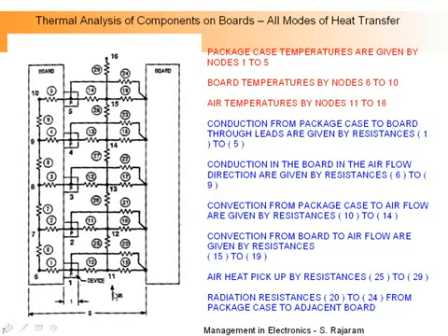So air comes in at, say, 20 degrees C and will be going out at each shelf maybe at 27 degrees C. And this package is dissipating heat, and it gets picked up and cooled as the air flows through. So that gives you an example that all these modes are available. So the trick is, what is the material property, what is the heat transfer coefficient, and those are the things that we use for analysis.